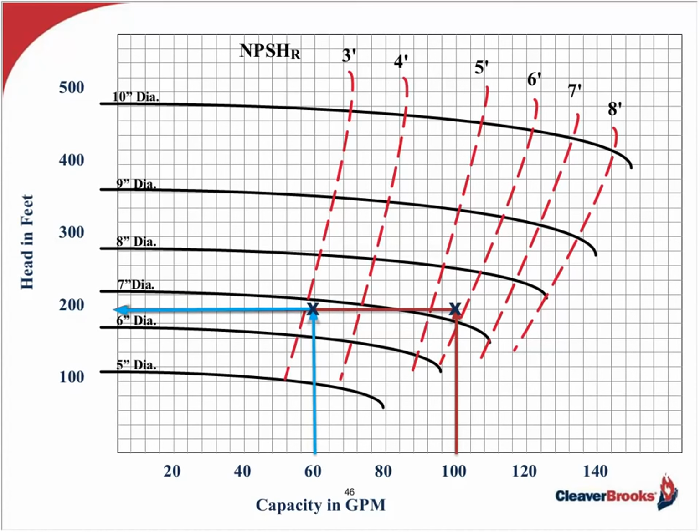Also note that changing the operating parameters and conditions of the boiler and associated equipment can also affect the size of the PRV valve, your makeup valve, and safety valves. So being attuned to possible impacts before making any radical changes can certainly save a lot of costs and certainly a lot of headaches in the future.